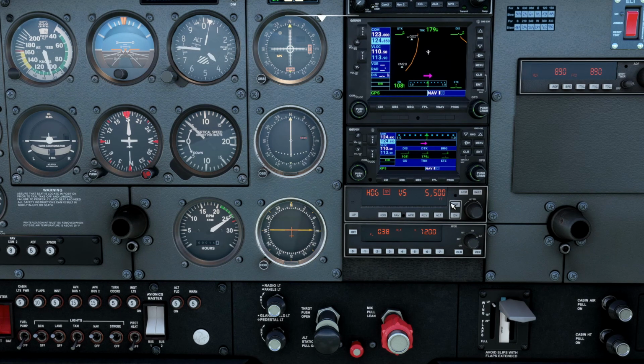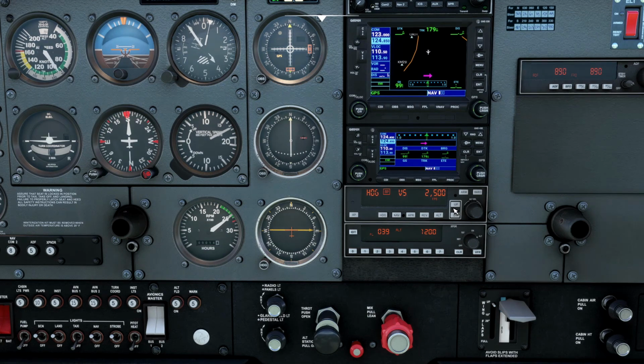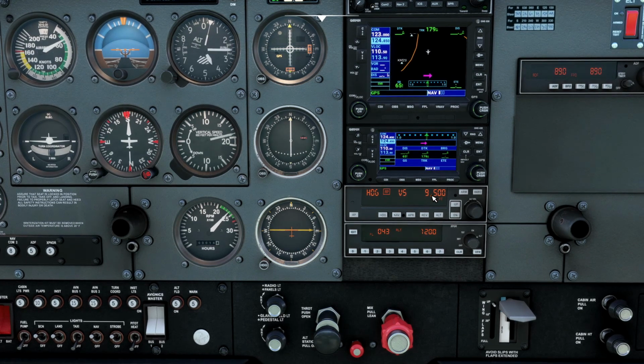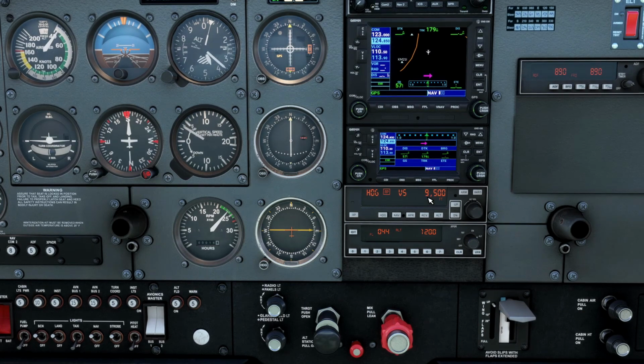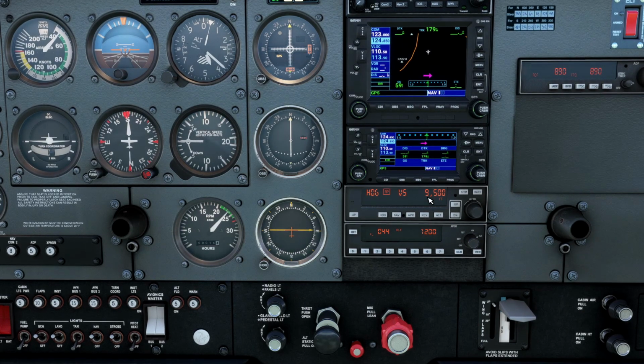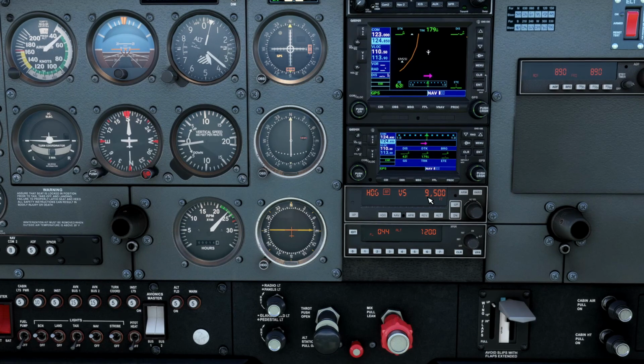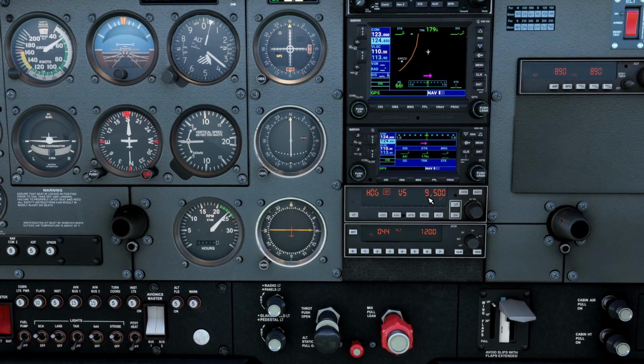One caution is that the system will try to do any vertical speed you set in here. So you can try to make this airplane climb at 3,000 feet a minute or 2,500 feet a minute, but there is no stall protection. It will fly you right into a stall. So be careful what you put in here. Pilots will often refer to these older systems as dumb and dutiful. They will happily do whatever you ask them to do, even if it means flying the airplane into a stall or flying the airplane into the ground. So be careful what you ask for.